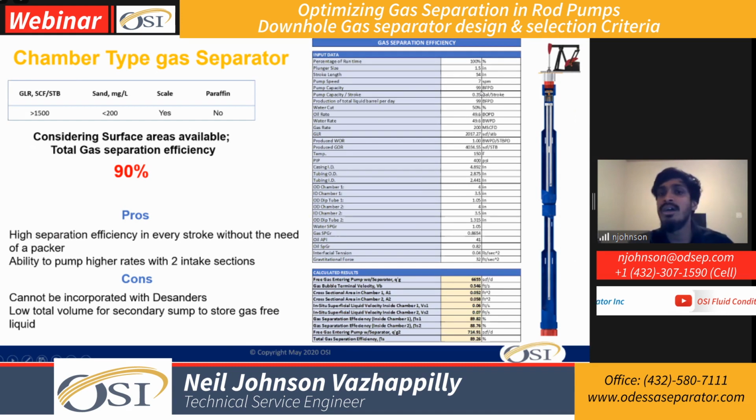As of now, considering a 48-foot chamber type gas separator in wells with high sand issues, since this section is isolated, we can definitely store some sand, restricting the intake of the upper chamber. If we use some tailpipes below the bottom section, we can have much more storage area. But the overall separation efficiency can be hindered by underlying issues of the wells that are not just gas.